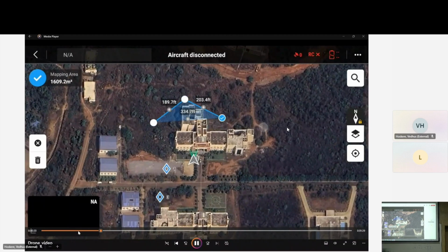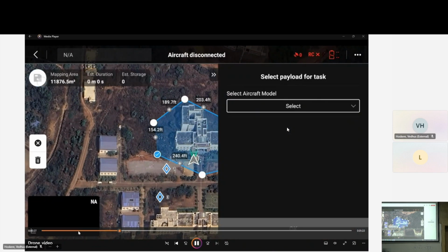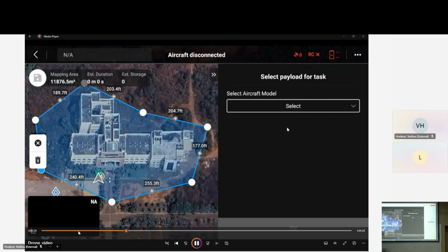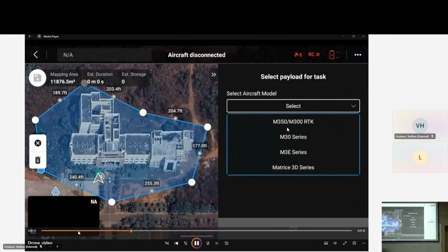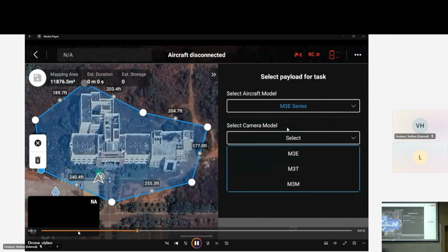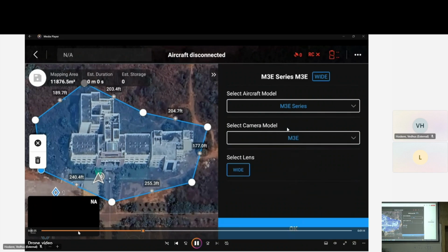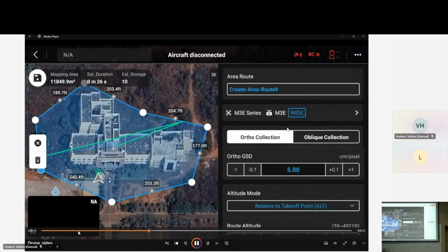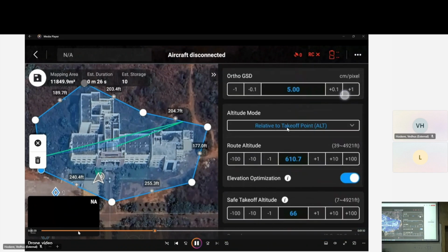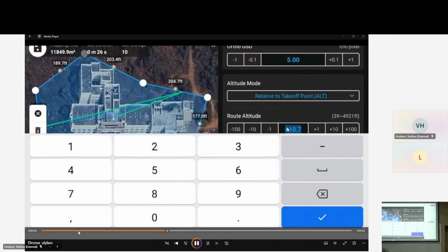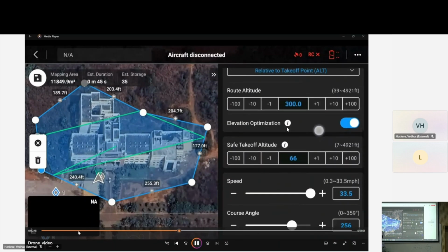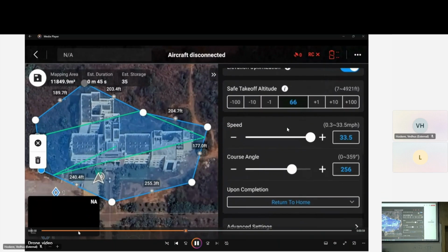Of what unit? Of centimeters? Is that the model resolution, or is that the ground sampling? I'm saying the model resolution will be 3 times that. Ground sampling distance is 1.5, so the model resolution will be 4.5. Yeah, so I think that's consistent with what I calculated, 3.6, 4.5.